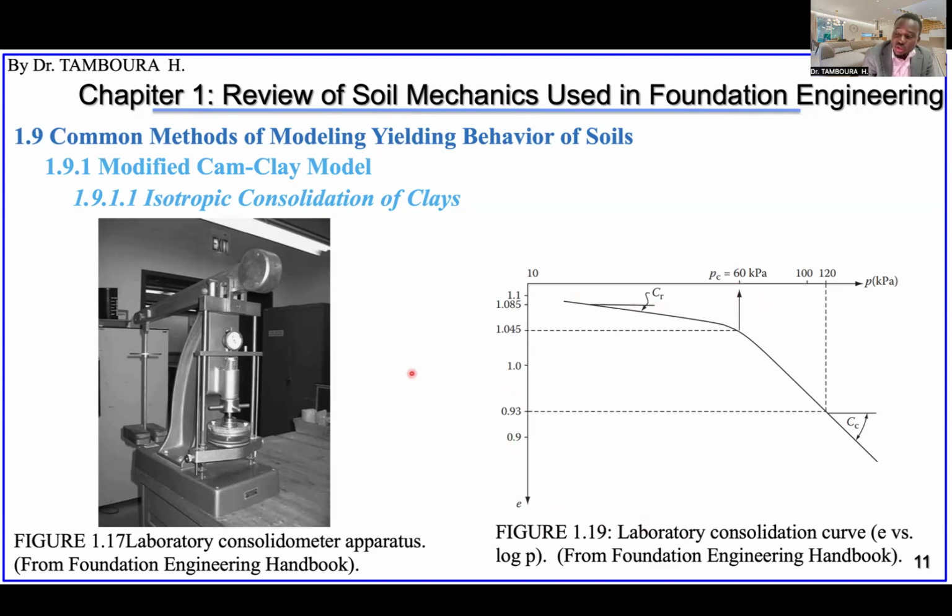If you don't remember, please go back in the previous video and you can find a lot of explanation about this. And we have several cases when you are in this situation, what will be the behavior, the relationship. Anyway, it is just about the stress and deformation relationship. So here, this axis is about the stress, right? And this is about the void ratio, the E void ratio. This void ratio is directly related to the volume, right?